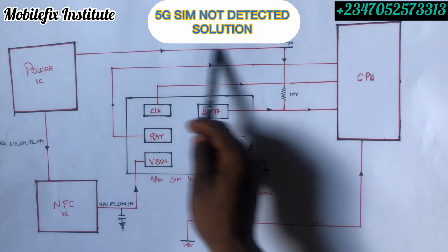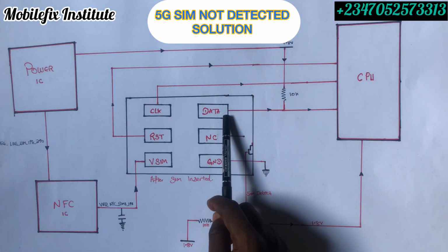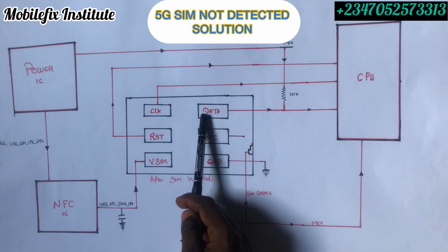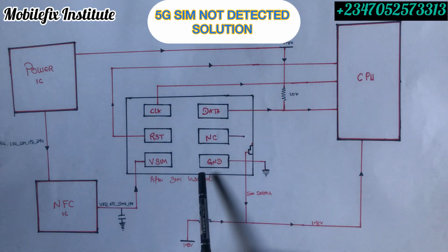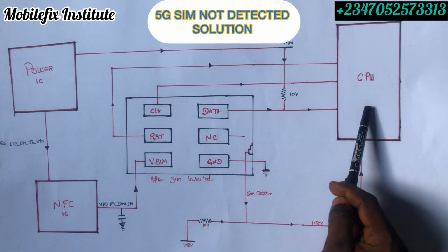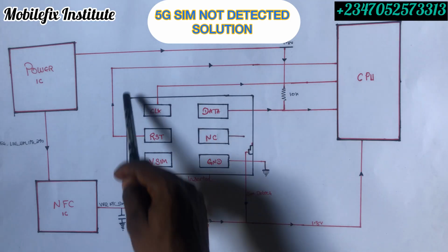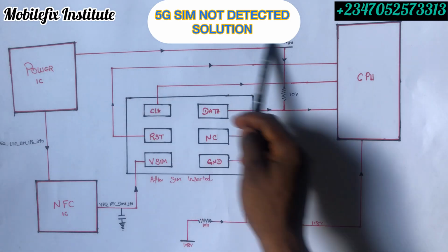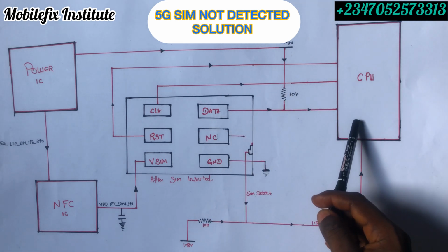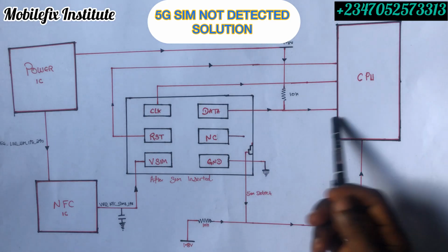Now test this side of the resistor, it should also give you value, and put it back, because it's possible to get value, but this line is broken from our CPU, because this is the power IC that gives you value. So all you have to do is remove this resistor, test it again. When you remove this resistor, you disconnect this line, you test it again. The CPU will tell you if it is connected or not, and after that you put it back. If you test this other side, if it's connected, it will give you value. When you connect it, you get your voltage. You only get your voltage after inserting your SIM card and your phone is switched on. So that is how this line works.